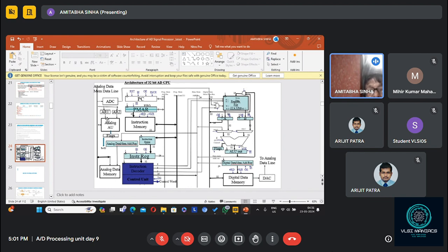Here you have to understand the basic analog circuitry clearly, how additions and multiplications are performed. This could be done by the operational amplifier. Secondly, the Schmitt trigger: any raw signal can be squared up by the Schmitt trigger to two levels, 0 and 1. These are very tricky and interesting to understand in analog circuitry.